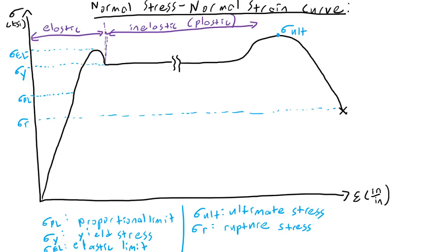When the outer fiber reaches the elastic limit, that's when you're leaving the elastic zone and entering the inelastic zone. Also, more critically, this represents reversible deformation. You can load this up until this point, and when you unload it, it will spring back to the original shape prior to loading.